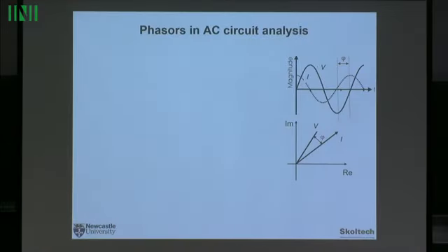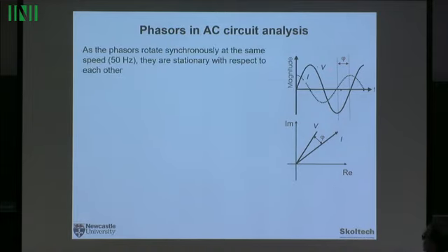So when you have two sine waves, voltage and current, you can represent them, the arrow has missed here, by those two vectors on the complex plane, and they rotate anti-clockwise. You freeze them at any instant of time. So the time shift between voltage and current, the angle phi, is represented as the geometric angle between two vectors. Remember, this is a time shift, and this is a geometric angle, and it simplifies manipulations. I said we call them phasors, not vectors, because it's the phase that is important.